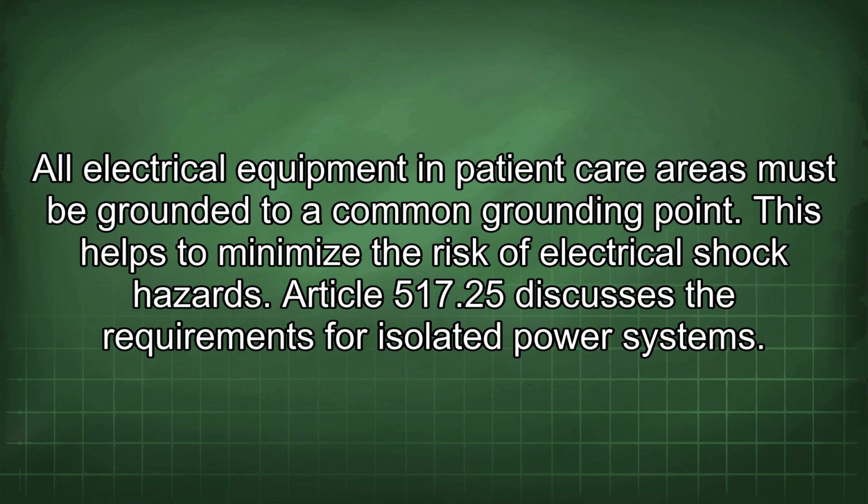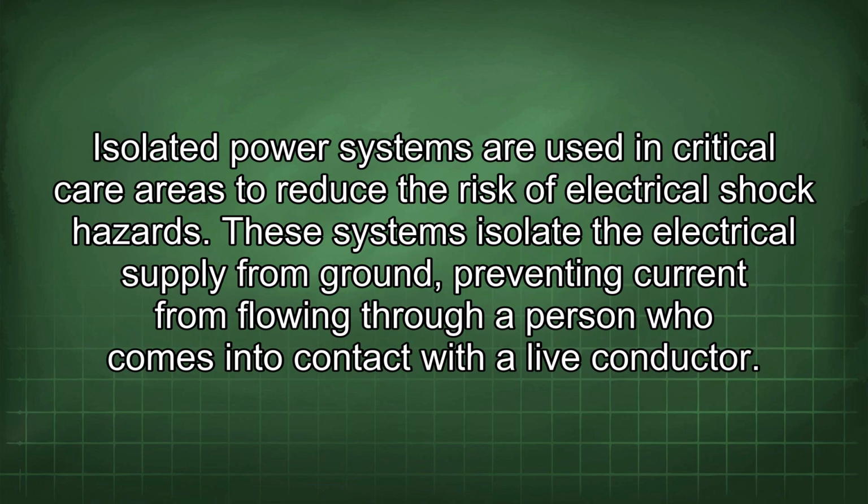Article 517.25 discusses the requirements for isolated power systems. Isolated power systems are used in critical care areas to reduce the risk of electrical shock hazards. These systems isolate the electrical supply from ground, preventing current from flowing through a person who comes into contact with a live conductor.